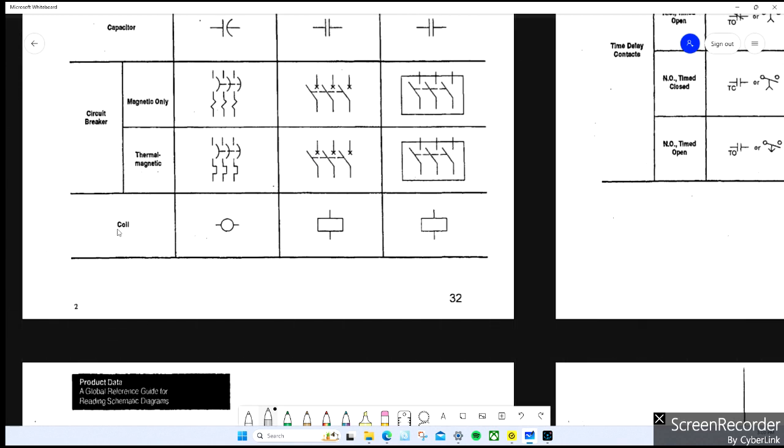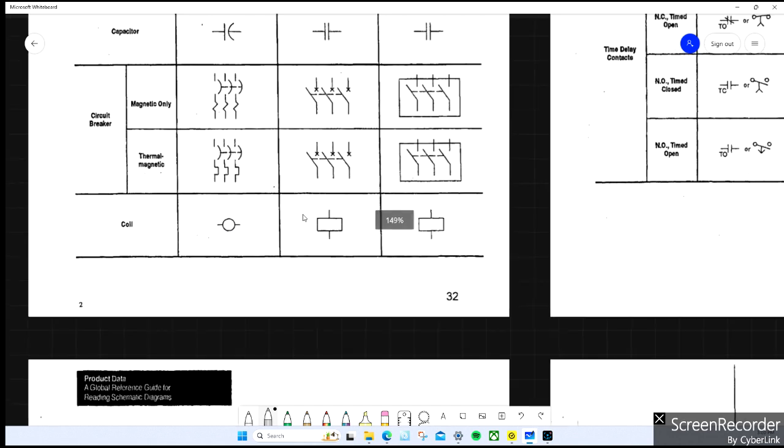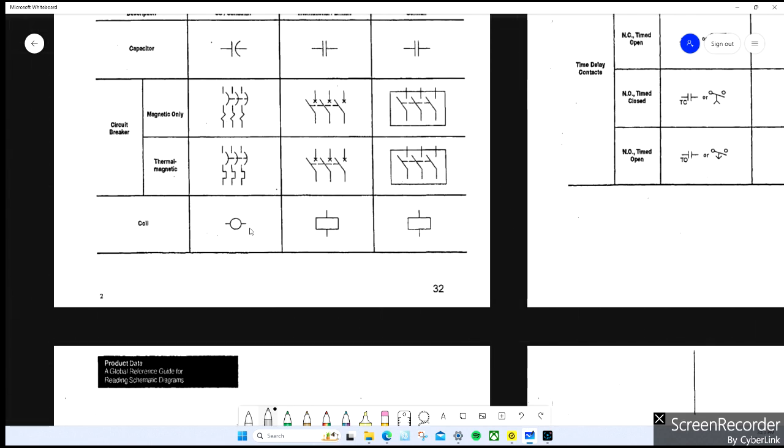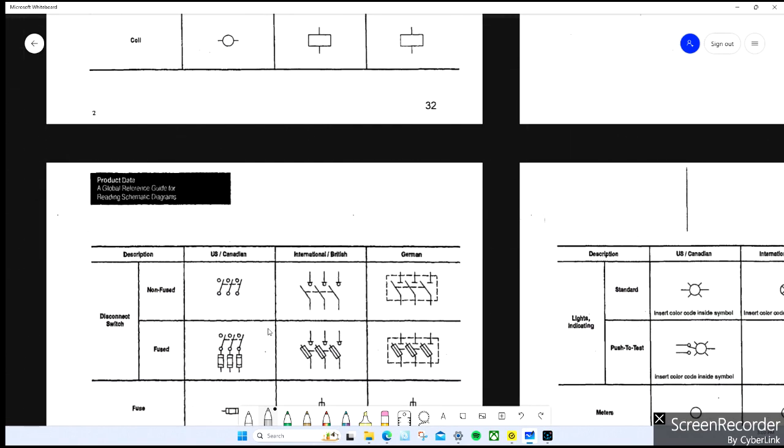So like a coil, right? Everybody knows what a relay is, and if you don't, Google what is a relay, right? And again, I will do a video later on what a relay is and how they work. Okay, but that would be the schematic symbol for NEMA. And then IEC, it's more of a rectangular look to it. All right, so a relay has a coil in it, we energize it. It basically switches a set of contacts that are internal to it. It's an electrical magnetic switch, we'll call it. Right? We'll talk about that.